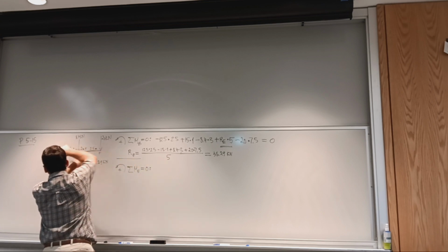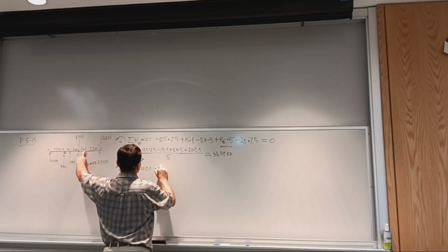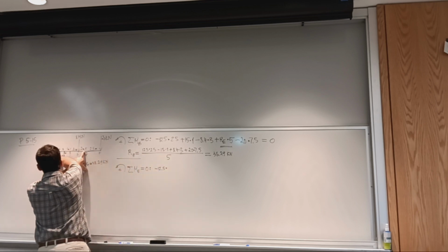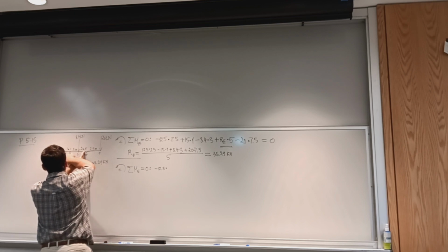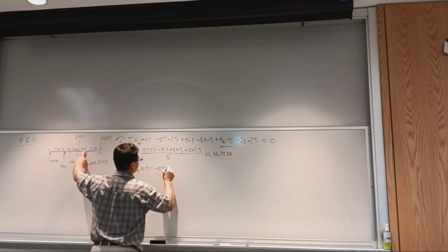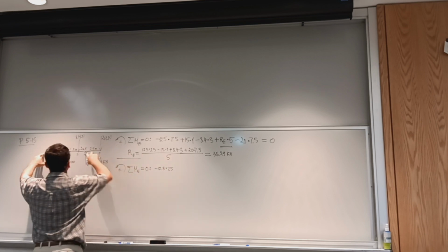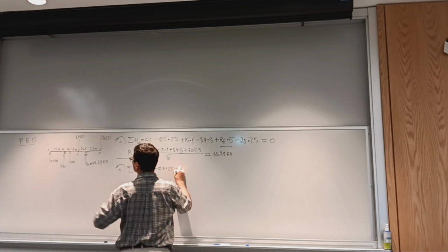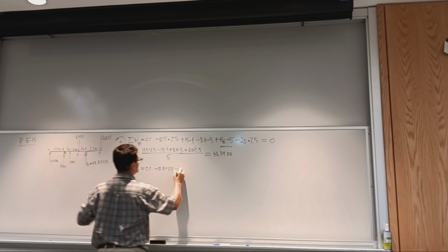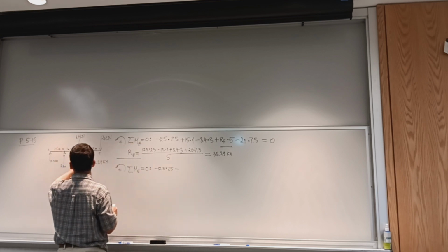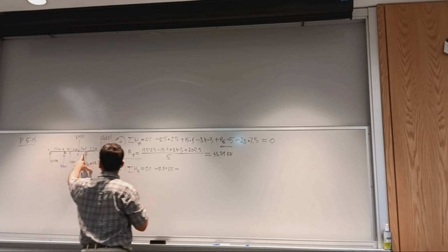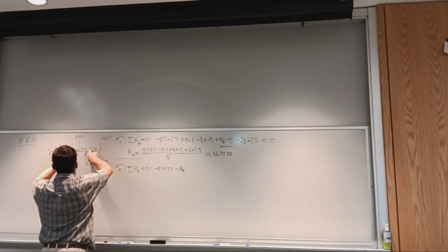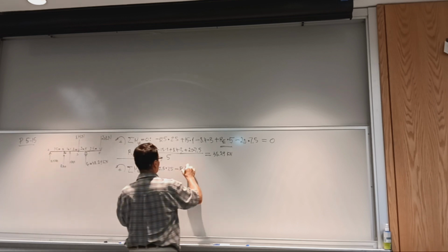The moment of the force at A will be negative. So I have negative 12.5 multiplied by the full length here, the length from A to E: 2.5, 3.5, 5.5, 7.5. Okay, 7.5. Next I have RB, and RB, as shown, causes a negative moment about E. So it'll be RB times this distance, 1 plus 2 plus 2, that is equal to 5.